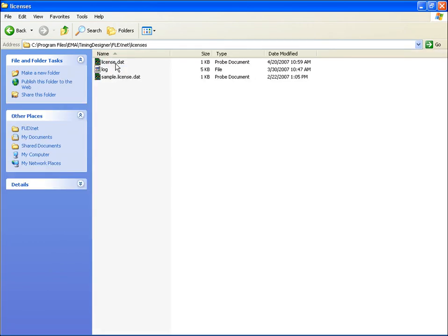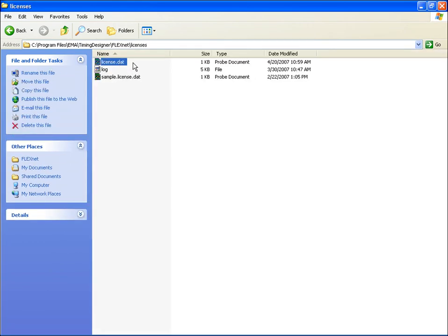This directory is recommended for machines that run TimingDesigner and also function as a license server, thereby providing a default location for the license file and eliminating the need for environment variables for node lock setups. For floating licenses where the license server is not the same machine running the tool, each machine will need an environment variable that locates the license server. More on this a bit later.